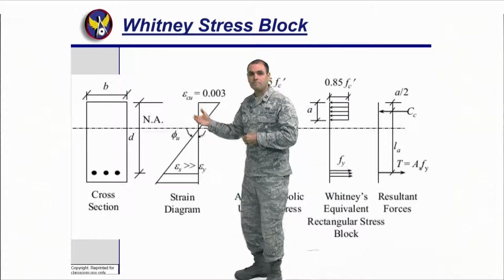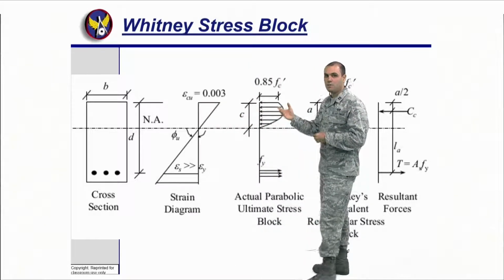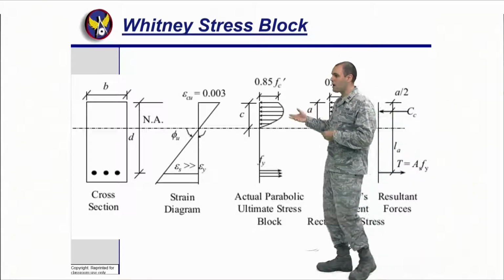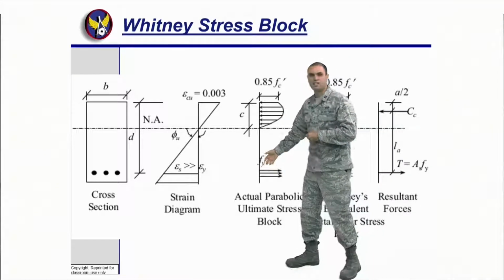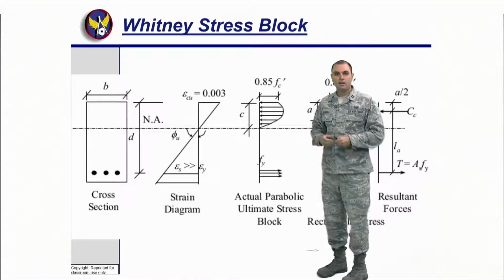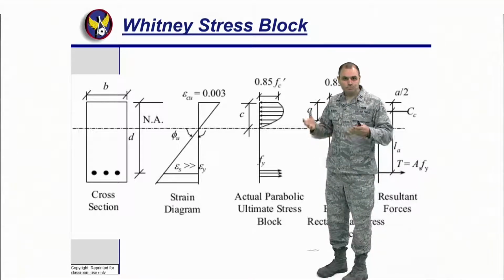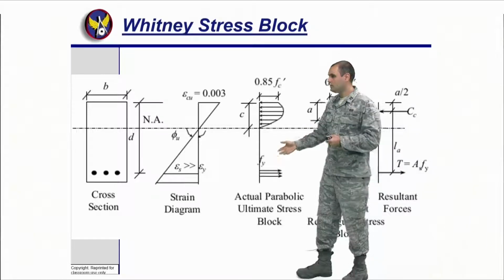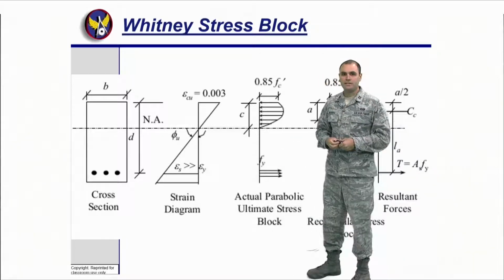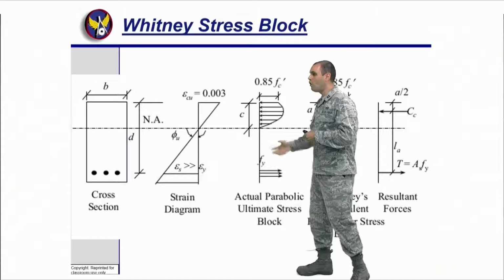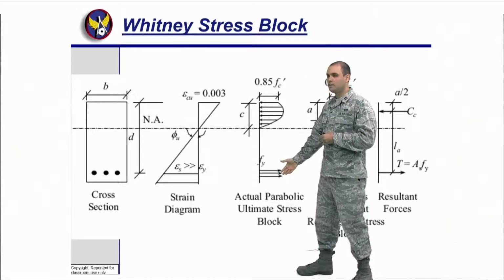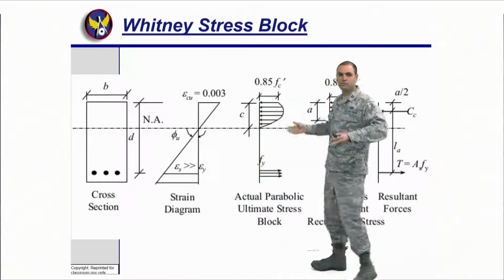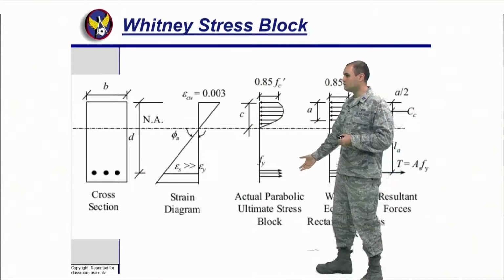As we go through it, we look at it and we say, well, what's the actual stress block? What's the ultimate stress block? Well, I know my top is in compression and my bottom is in tension. But you already said that concrete is bad at tension. Yes. Therefore, what's really holding the whole beam in tension? The steel rebar. And that's why instead of seeing a whole area here, you see like 3 lines. What are those 3 lines? I'm talking about the 3 rebars, but if you have 2, then it's 2. If you have 1, it's 1. In essence, it's just 1 line.